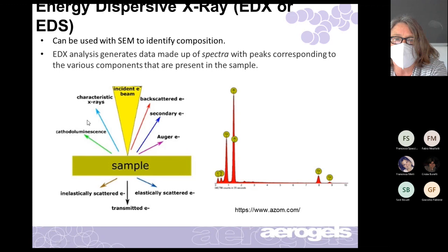There are a couple of things that will give you. You can look at a sample and have it tell you what its chemical composition is. You can extract a spectrum like this, which tells you what chemicals are in there. This particular one has some copper and some alumina and some other copper. Now these X-ray spectra have signature peaks at different locations, and some things can overlap, so it's not always perfect, but if you know what you put in, you can search for that in your sample.